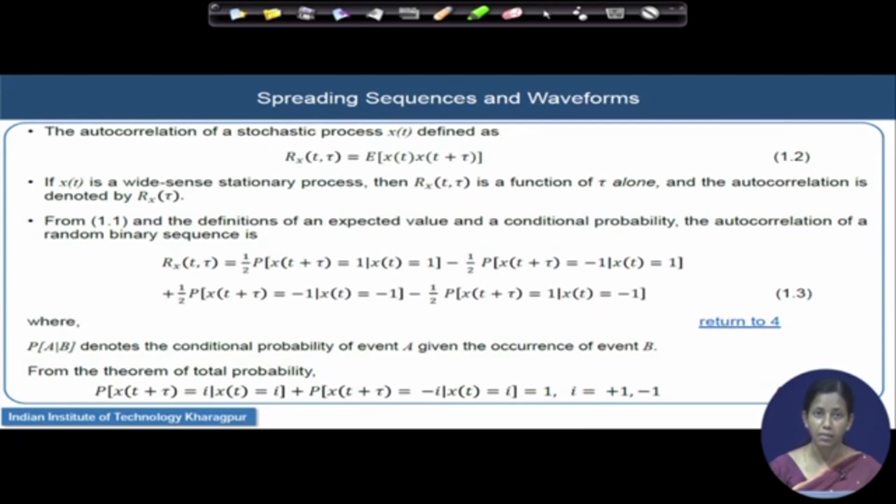This is a typical demand for the autocorrelation property of any spreading sequence, and those kinds of sequences are most preferable in our system design, due to the fact that they give very good demodulation and despreading. At the end of the despreading, you will get a good difference between the desired signal and the jamming one, and your signal energy won't be spread much onto the side lobes.